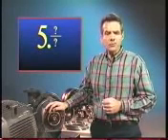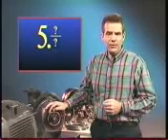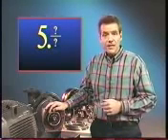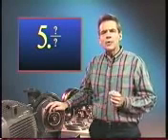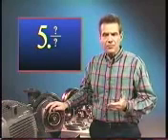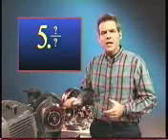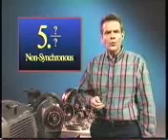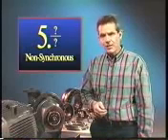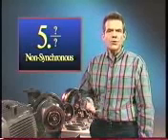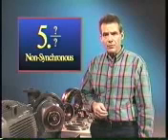This is the key to differentiating between bearing faults and other faults, such as vane pass, which would show up exactly 5 times for an impeller with 5 vanes. This fractional energy is called non-synchronous energy. That is, it is not a whole number multiple of the shaft turning speed, like 1.0, 2.0, or 3.0 orders.